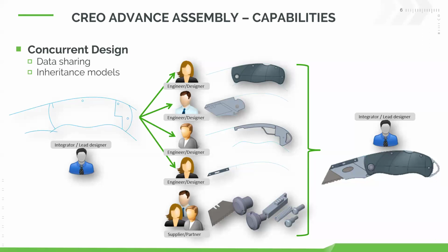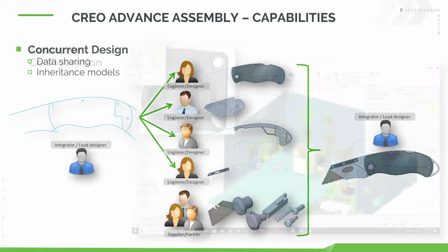Another thing that we use here a lot of times is also inheritance models. This is controlling whenever you make changes to a certain part or some assembly, you can create inheritance models that those get cascaded down to. The idea is maybe you have certain parts for this blade that's going to be your design model, but then maybe you have another one that's going to be your finite element analysis model where you do some defeaturing, or there might be one for manufacturing where you're taking into account, say, shrinkage, for example. You can make those modifications and then have a lead inheritance model, almost like the parent model that these changes all get cascaded down to, but the changes on each individual level don't get made. So a very powerful tool that we see a lot of our customers working with there.